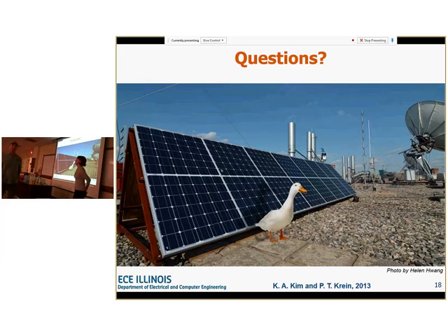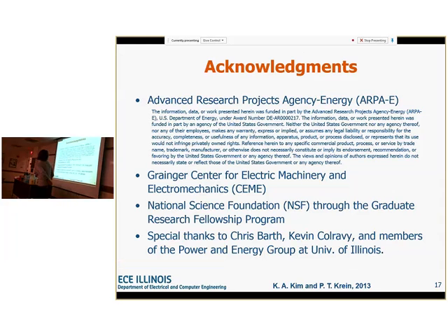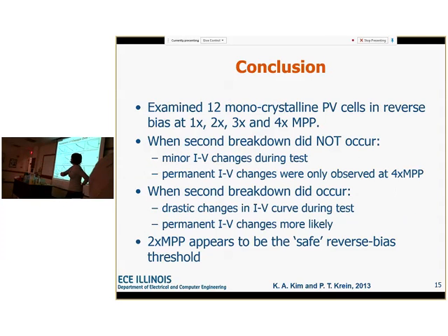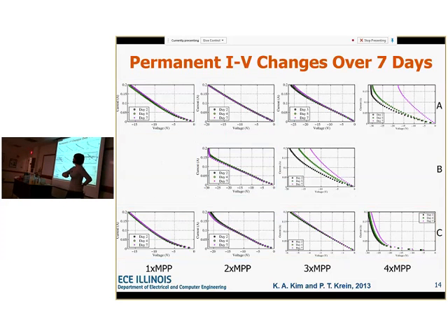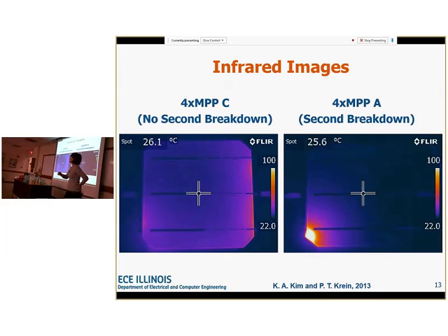So I was wondering if you did the thermal imaging thing at each time. Does the hotspot move? Is it always in the same spot? Once, is that just a defective part of the cell or something? I did not do it every single time, but I did it on a few, and it always comes up in the same spot.